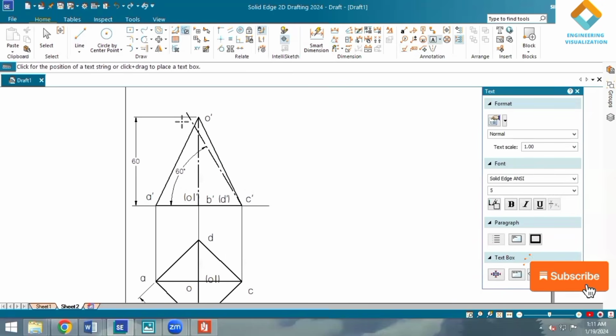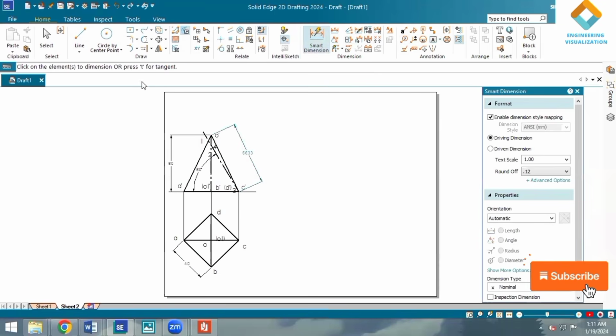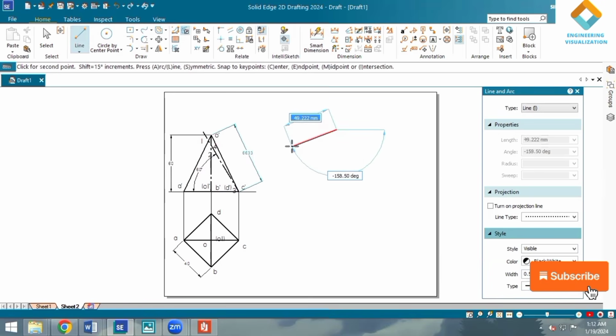So cut point 1, it is cutting on a slant edge AO, and 2, it is cutting on a slant edge BO. Okay, and cut point, it is occurring at the extreme corner 3. Okay, 3 is occurring at C, and then 4, it is cutting at DO, that is slant edge. Okay, so cut points are mentioned, and this is what our slant edge, because the CO slant edge is parallel to XY. No need to find out extra slant edge, it is already available. So draw a straight line for length of this slant edge length.